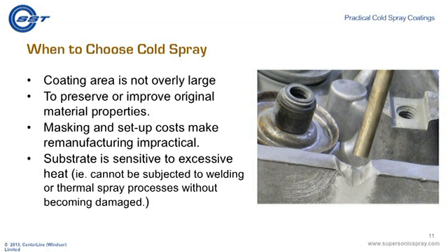If you're currently using any repair processes that incur excessive masking or setup costs, you will want to consider using cold spray. If your substrate is sensitive to heat, in other words, it distorts, or you're working with very thin metal materials that can't accommodate any heat processes, you will consider using cold spray as a repair tool.